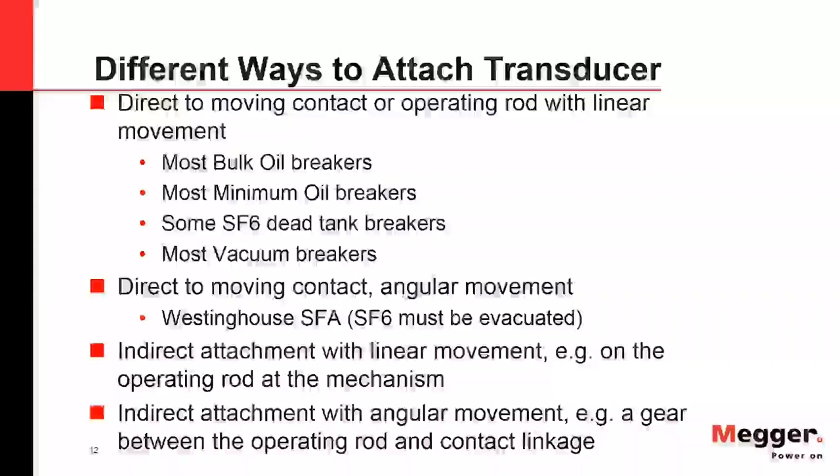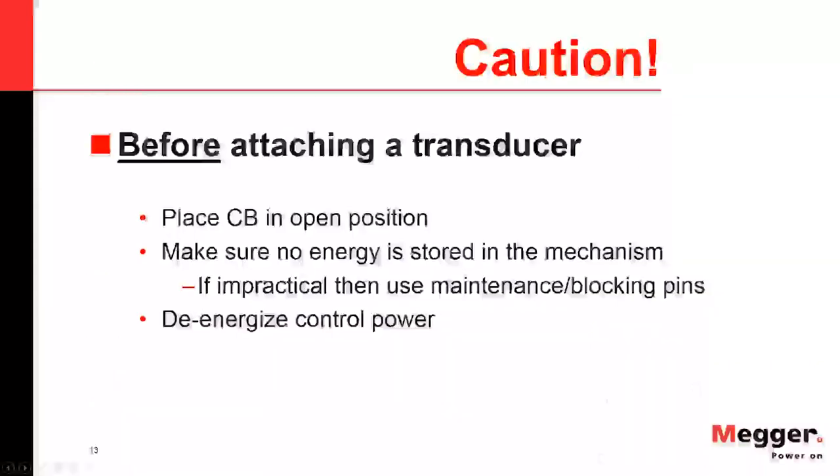And you can also do this with an angular, rotary transducer, where you have an indirect attachment to get your angular movement, putting on a gear or a spline or something between the operating rod and the linkage, and then converting it over with the conversion factor.